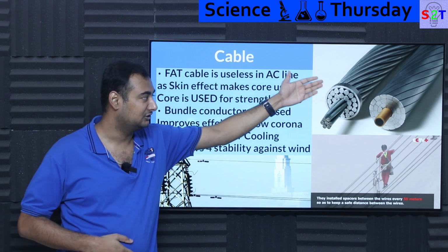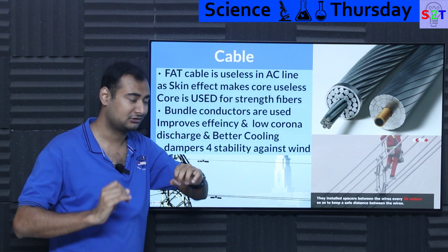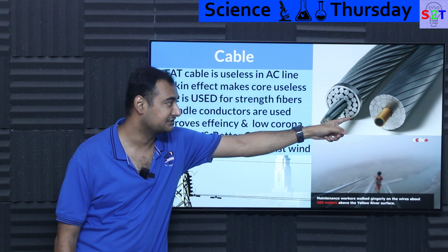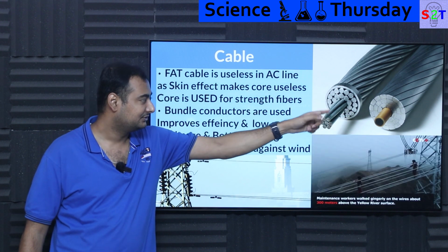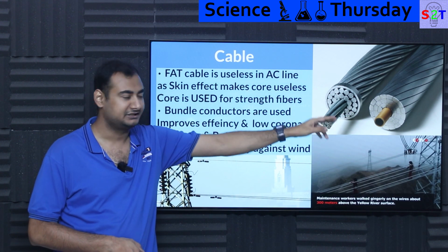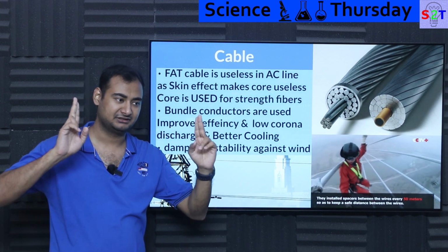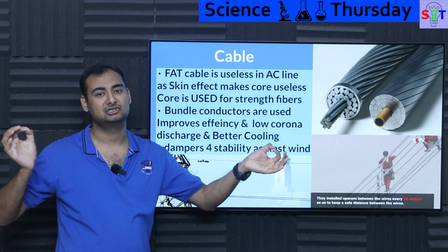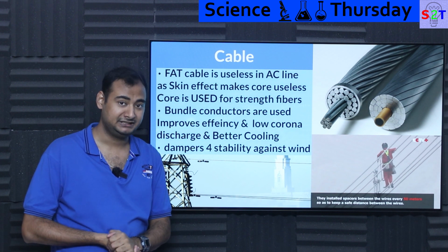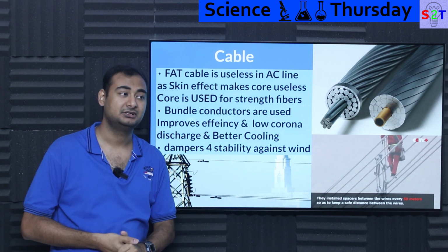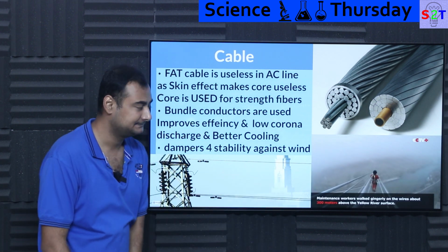Somebody's like, what if we take aluminum and mold it into a much tighter tolerance, much better shape for higher skin efficiency, and replace the steel core with basically carbon fibers? That's the current cable nowadays. Benefit of carbon fiber is that the span between your poles can be much longer, like 10 to 30% longer, meaning over a distance of, let's say, 100 kilometers, you will save the number of poles you need.